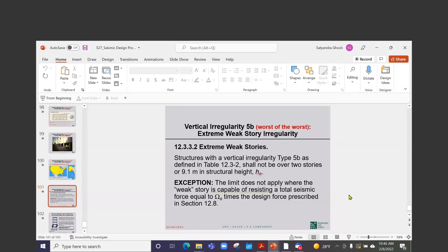But if you want to be code complying, I went over that, I think, on the first day of Seismic. There are serviceability load combinations in BNBC. So look at that. It tells you to keep gravity on the structure.